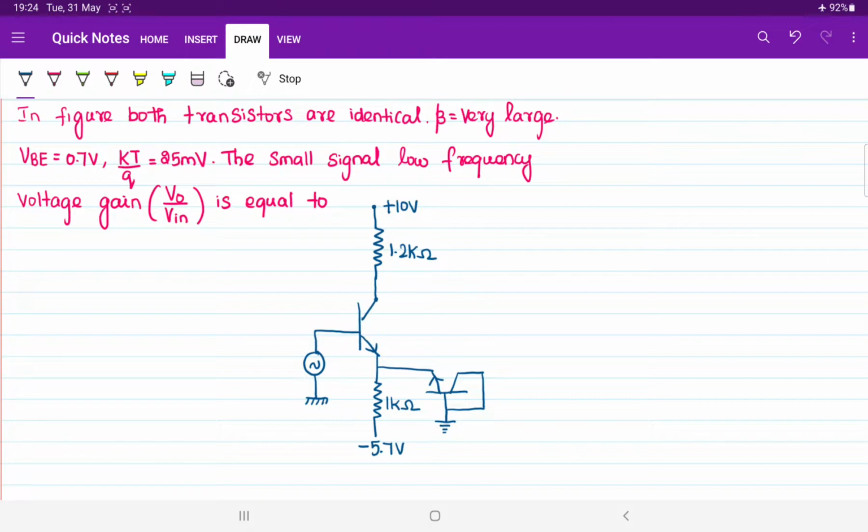Basically, our bipolar junction transistor is connected with two supplies. One is DC supply, another one is AC supply. When you are analyzing the circuits in the DC domain, suppose you are requested to calculate the value of emitter current, emitter to collector voltage or base resistance. These kinds of parameters can be directly calculated in DC analysis. So when we are doing DC analysis, we directly short all AC sources and remove all capacitors, because in DC analysis a capacitor always behaves as an open circuit. That is what we usually do when doing DC analysis.